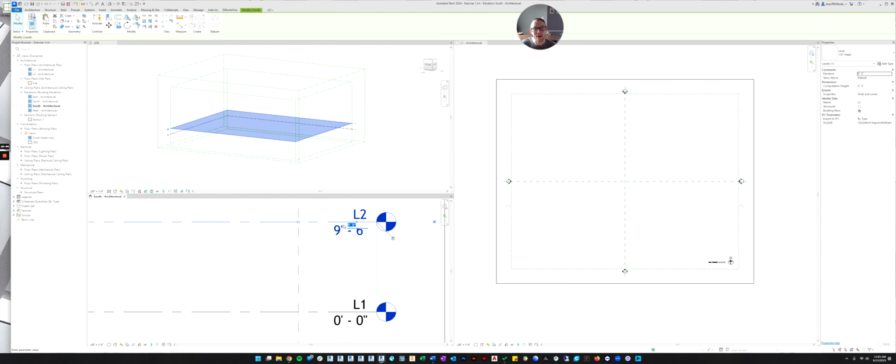Okay, so there's lots of ways to enter dimensions, but just remember, if you just put a number in and don't put any other information but the number, it will assume you mean feet. So let's say I want to do 10'6". You can do 10 apostrophe space 6 and then quotation marks and then hit enter.